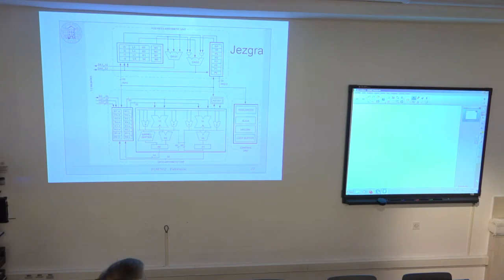And then this I is always relative to this B, but modulo L, okay? In this way, I can put this buffer any place in the memory as I desire. I don't have this restriction that the first address of the buffer must be on an integer multiple of this convention, that is, the first larger power of 2 than the modulo.